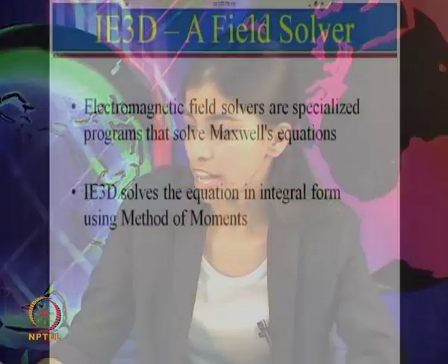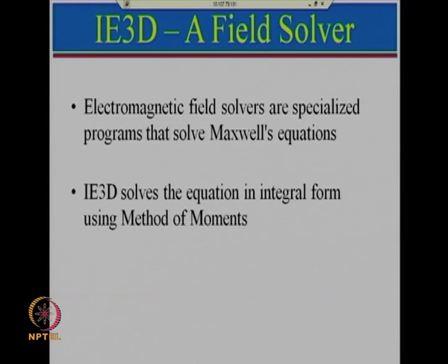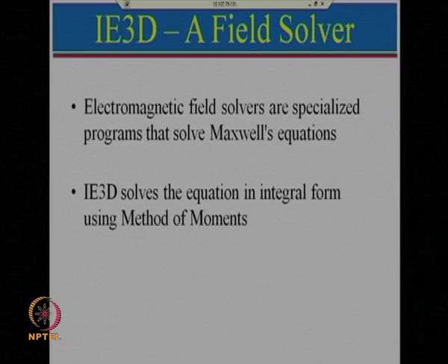So, let me now start with the basics of i3D. i3D is a field solver which solves the electromagnetic field equations with the help of integral equations. It utilizes the method of moments, which is based on the Green's function, which is basically based on the weighted complex residual method. Now, let me tell about the i3D application programs and capability.